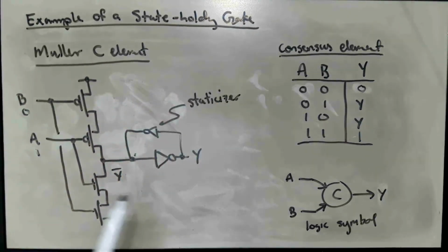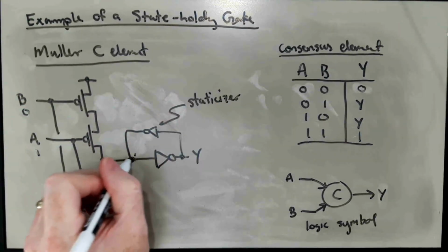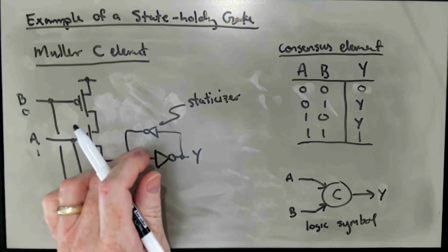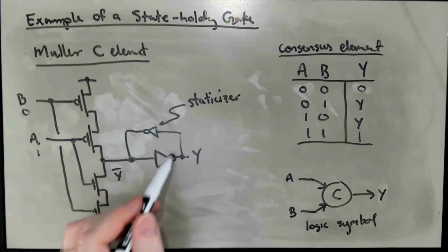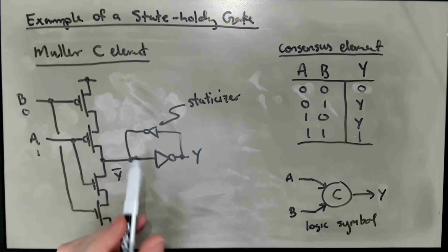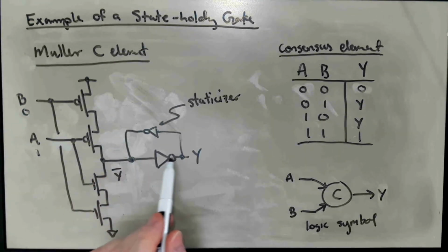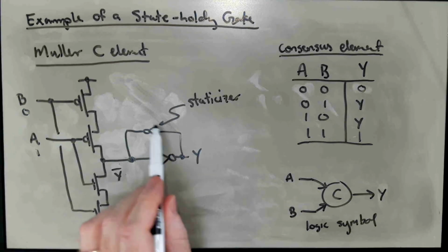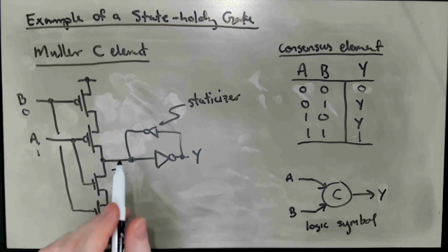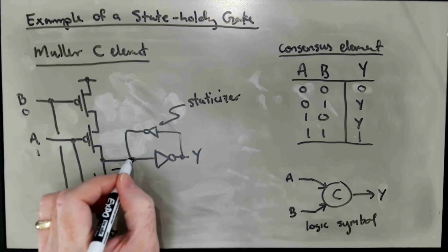So it takes a dynamic implementation of a gate and it turns it into a static one. So here we've introduced a bistable element into the output of the gate that will have the ability to store a bit of information statically by the presence of this feedback here. We're encoding that in the stable states of this dynamical system.